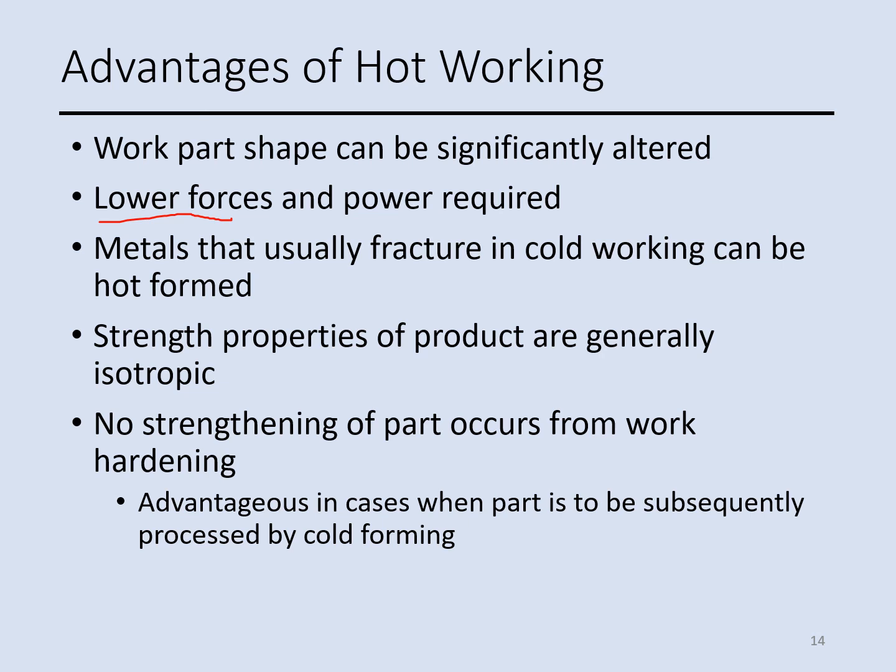And the strength of the part, the workpiece, becomes isotropic in the hot working process. It means the material property is going to be the same in all directions, x, y, z, and the part will have no strengthening.